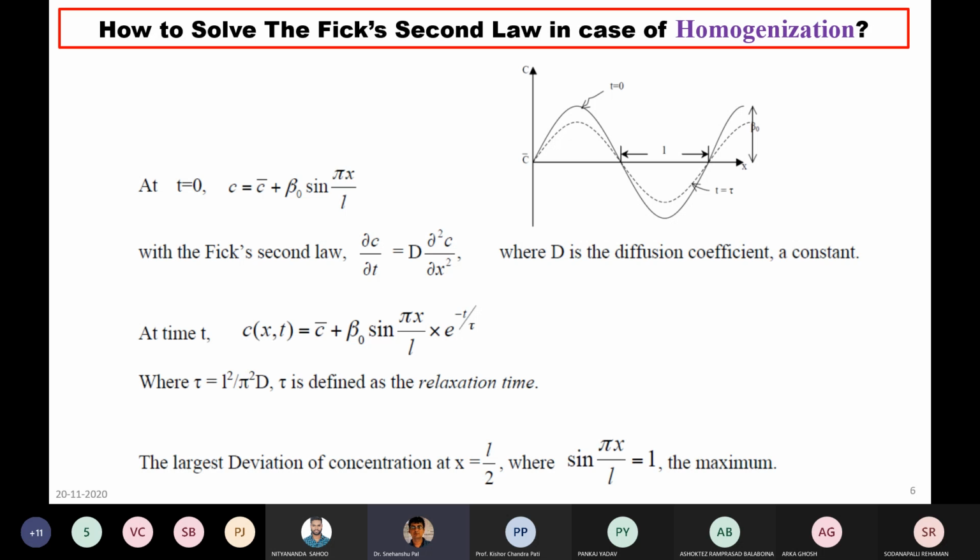So you have observed the picture. Now we try to explain it. Here we are discussing one case of homogenization, where you can take the annealing process for a very much longer time. So the concentration gradient will be reduced to 0 so that the whole specimen will be homogenized. From non-uniform to uniform, you want to get the concentration profile inside a specimen.